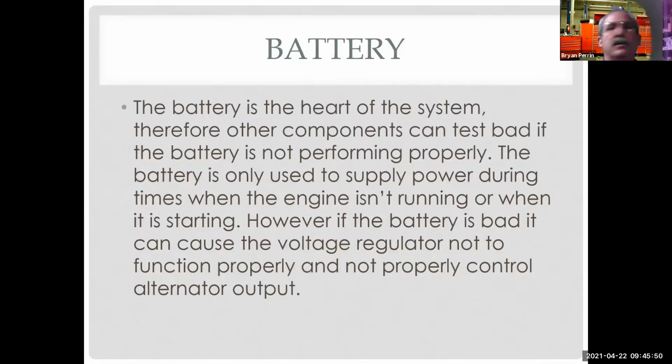Since the battery is the heart of the system, other components can test bad if the battery is not performing properly. One of the mistakes people make is they think if their car starts, their battery's good. Wrong answer. A battery can be bad and still allow a car to start, and still have other systems that don't work correctly because the battery's bad. The battery is only used to supply power when the engine isn't running or when it's starting.